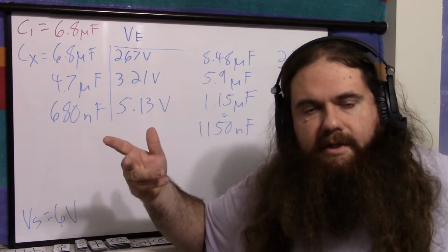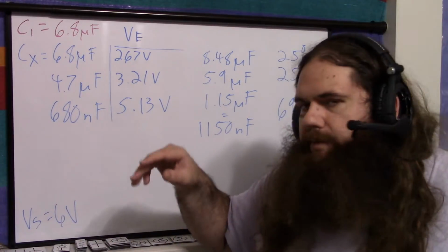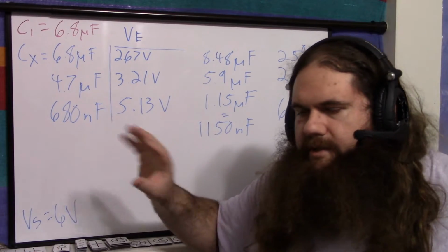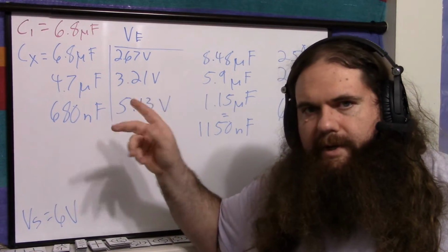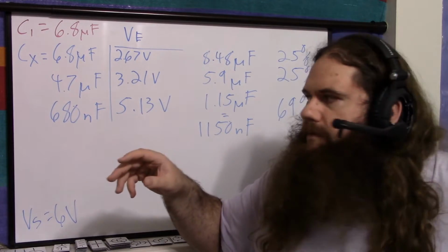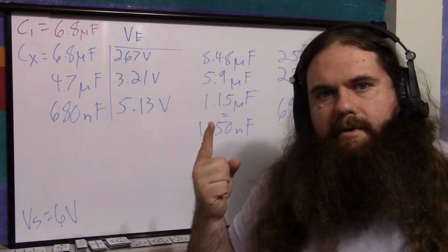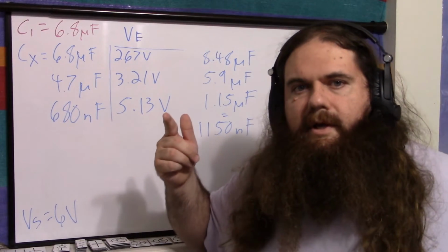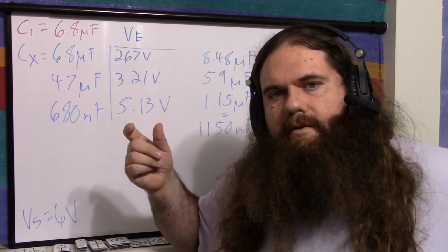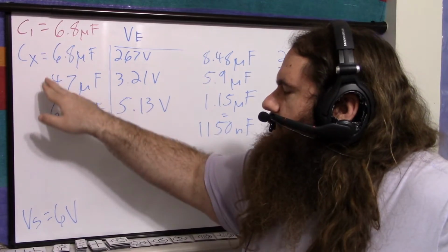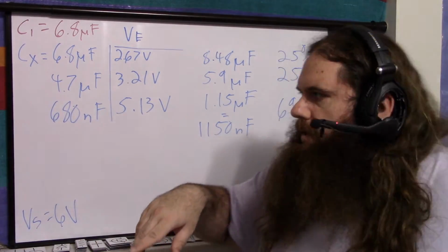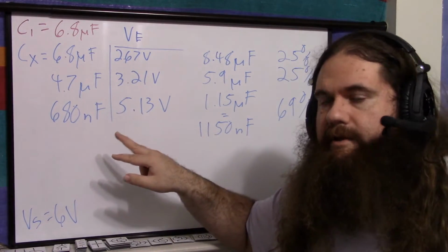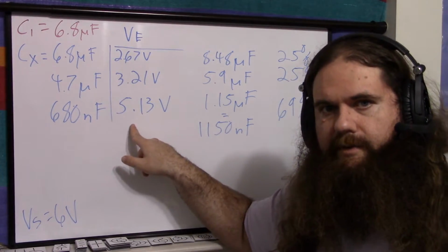I would be using my oscilloscope instead of a multimeter. But you're really only dealing with the variances of the capacitors. And you're just calculating using those variances, and that's why we're getting that error that's within the capacitor variance. But then I'm assuming, in order to get the expected voltage, remember we assumed the value of the unknown capacitor. So you've got variance in this capacitor, variance in this capacitor, and then I took this voltage, which already has these errors in it. The variances of the capacitors is already in the voltage I measured.